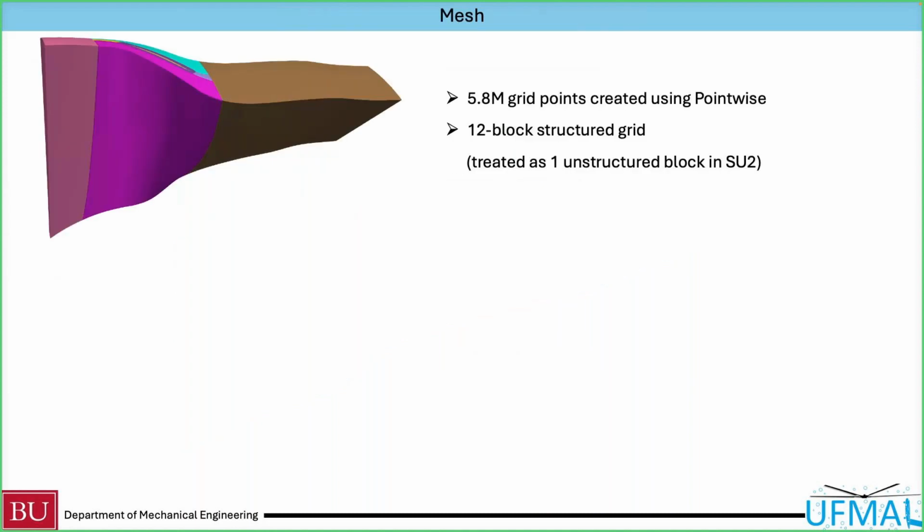For the mesh, it is a multi-block structured mesh created using Pointwise. There are 12 blocks in total, and they're treated as a single structured block in SU2.